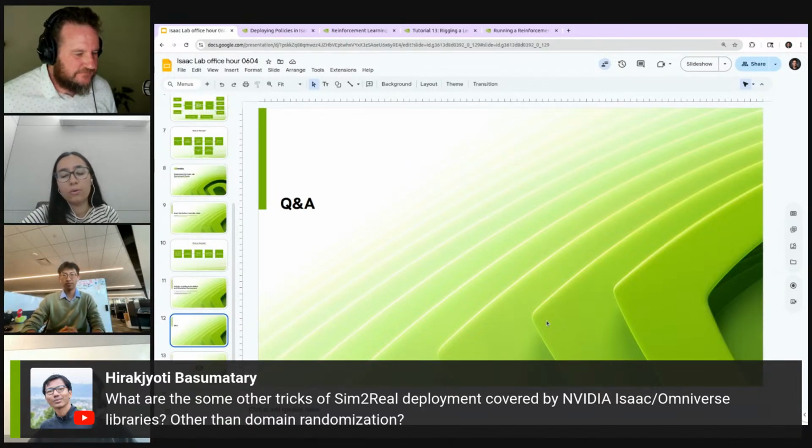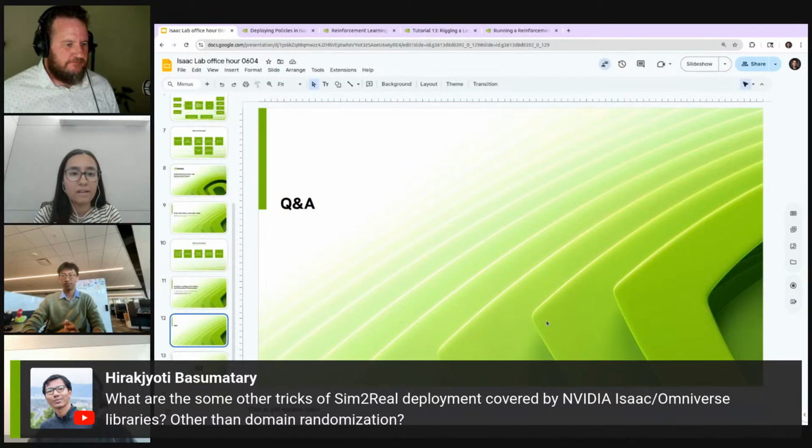So in that case, what you're doing is essentially running the software that you want to test on either the same computer or another system, like an edge device, and you use Isaac Sim as the environment the software is running in. Testing in the real world is dangerous, so you do it in Sim, and you can get fairly robust behavior in Sim and then be sure that it'll behave very closely in the real world. So that's software in the loop, another trick.